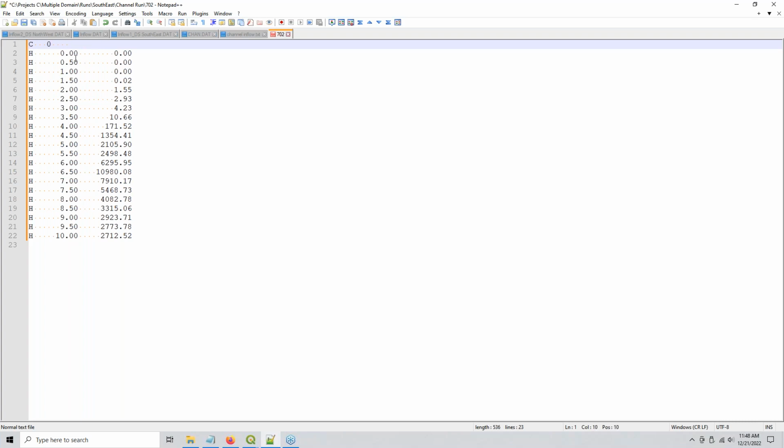0 is an inflow node, so the hydrograph is added to the system. 1 would be a diversion, meaning water would be taken away from the system. And then the grid element number, which is the channel, and of course C is for channel. And then you could take that into your downstream Southwest model.